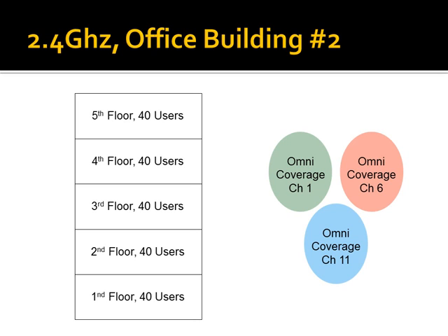So my point is, when you're looking at these kind of solutions, remember that you have power as a variable, you have antenna pattern as a variable. Look where your energy needs to go. It's probably the most overlooked solution piece. Because everybody thinks, oh, I need to do omnis. No, you don't.